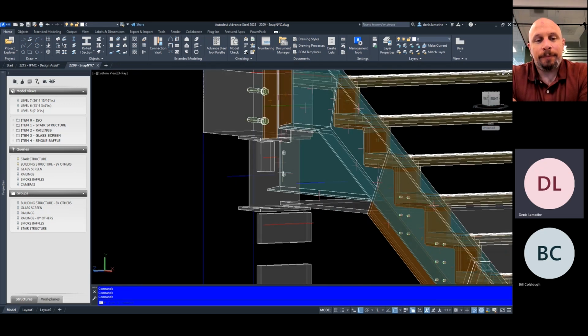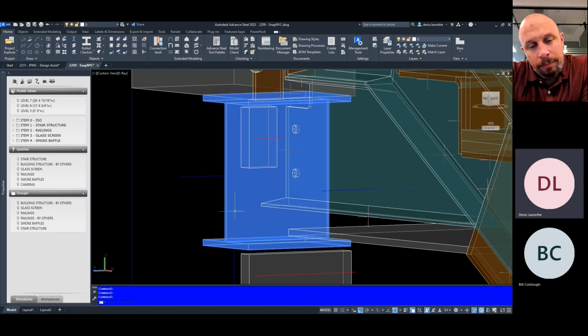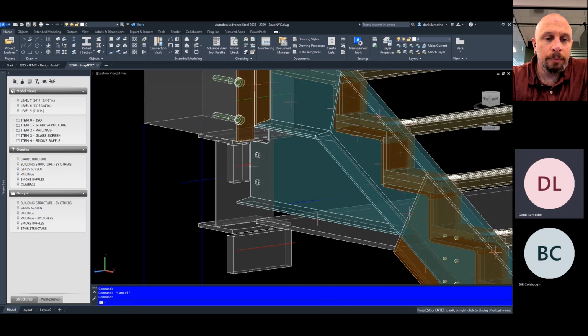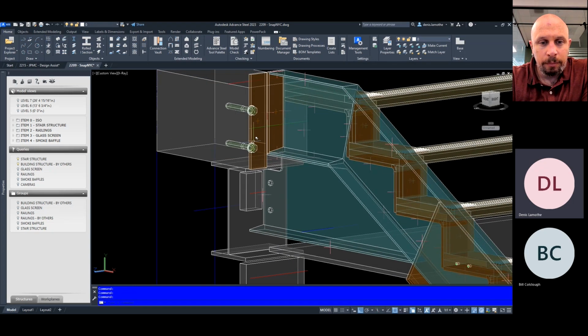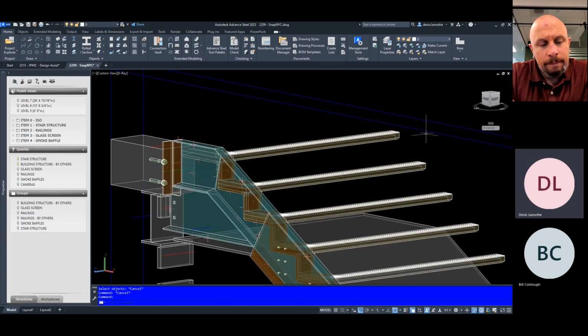But we would connect to the steel beams in this case. We'd have either plates or modify a stringer in some way to clear the flanges and the webs. And we would bolt or weld on site to the beam, or it could be an HSS member that's under the floor. And that would be one connection type. The other connection type would be similar to what was at the bottom of the stair that I showed you in a previous example, where you'd have a connection plate that would often span between the two stringers, with multiple anchors patterned across.